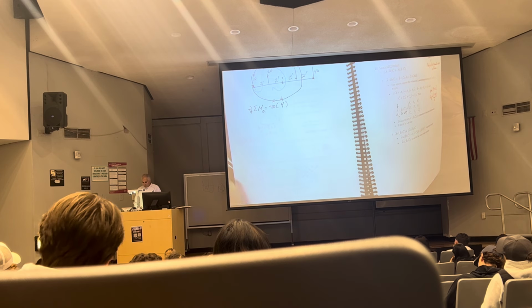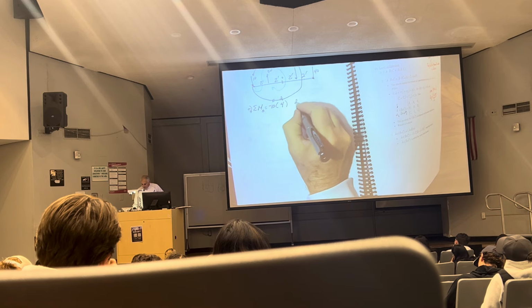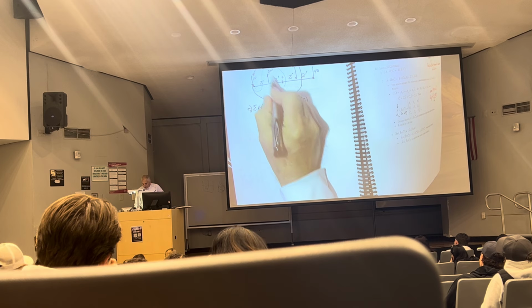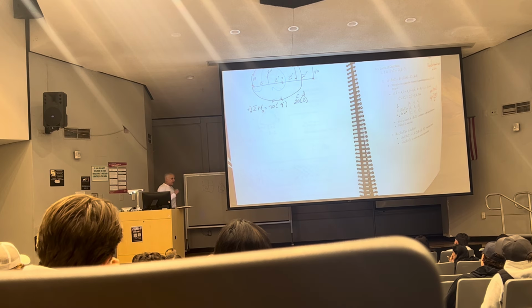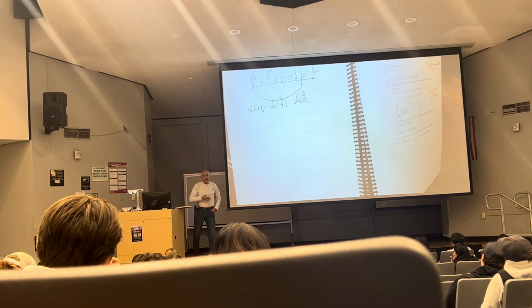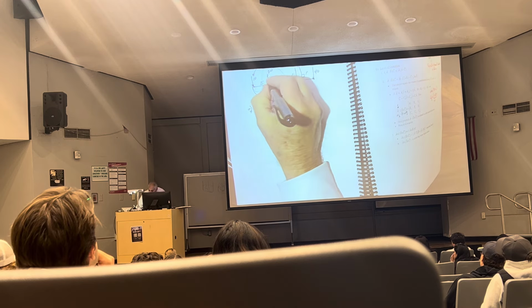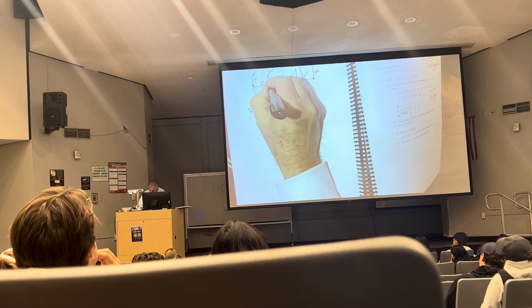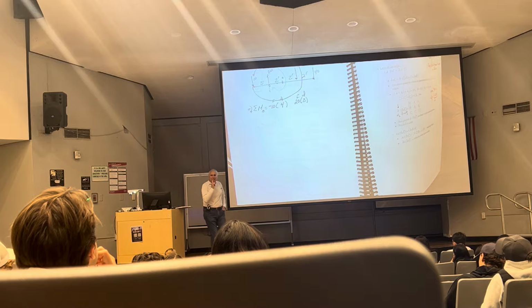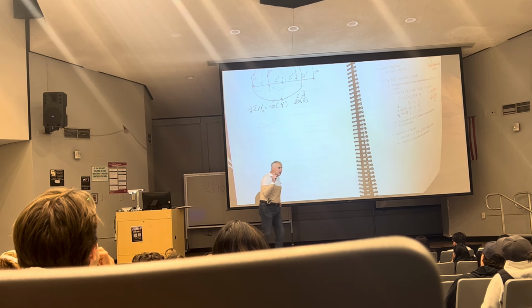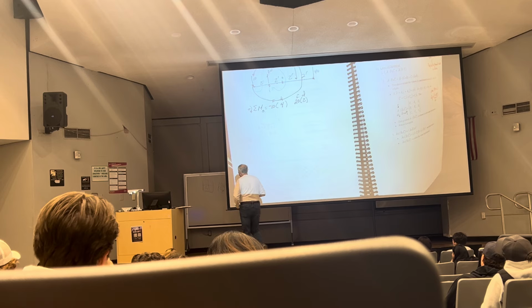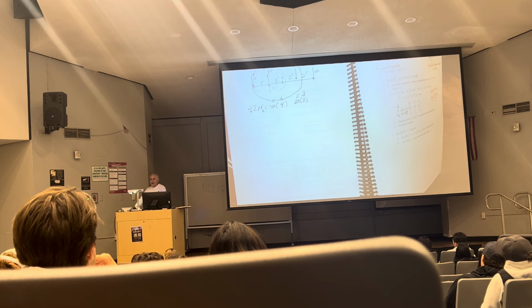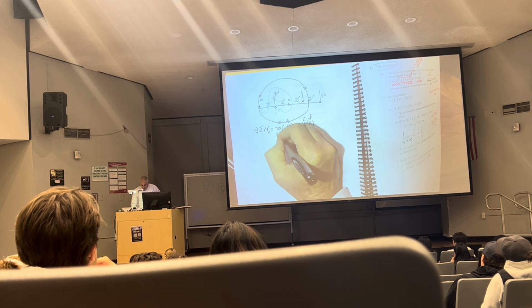Counterclockwise. Okay? Next, I know this is 20 times 2. 20 times 2 gets me there. There's the force. There's the distance. I have to have a sign. I'm going to now move this to here. What allows me to do that? Correct. Transmissibility says I can move this force anywhere along its line of action. So I can move it down to here if I wanted to.